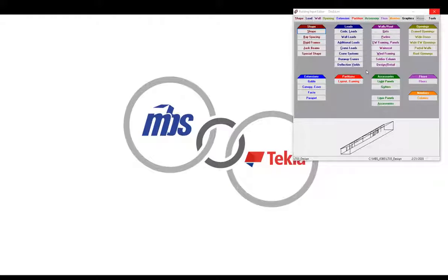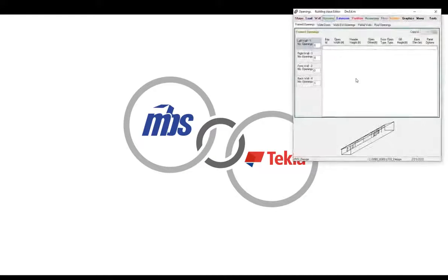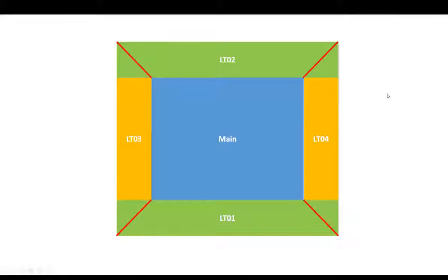The lean-to sections of our building are set up in a similar fashion. Here under the shape section we can choose a lean-to type, enter the overall dimensions and heights, all the same type of information, again including things like openings. You do want to make sure when you're defining your lean-tos that 2 of them are going to project past. That way we're getting full roof information going all the way out to the corners, and then 2 of them would be kept a little bit short because in MBS we can't have building sections that are overlapping with each other. That's the type of work that will be taken care of in Tekla Structures once the overall building design is completed.